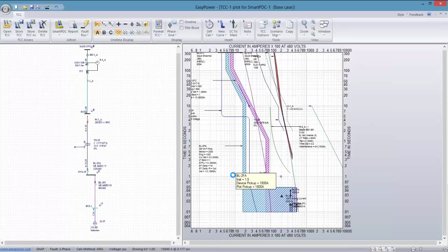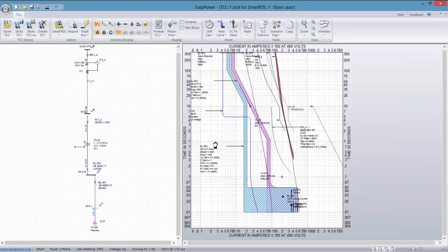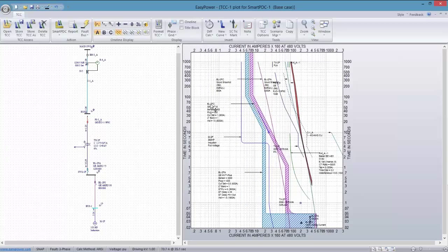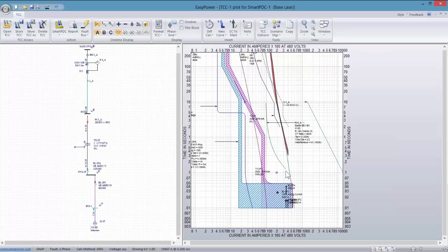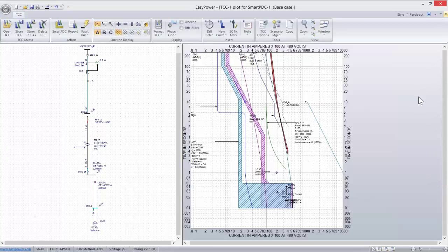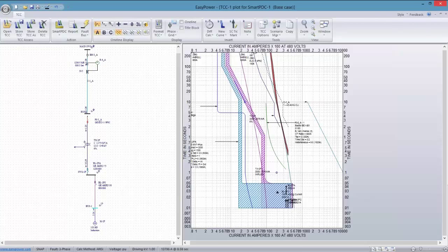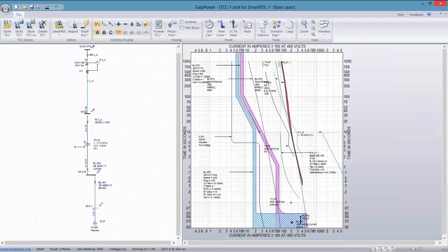All right, so you can see where we have some very obvious miscalibrated settings between the downstream breaker, the second breaker upstream, and then the relay. So apologize for taking the shortcut, but at this point it really does need, if you will, engineering work. It's more than just a review of the settings. We can see the settings are wrong, and so at that point we would want to have an engineer look at what the settings ought to be or analyze what the settings ought to be.